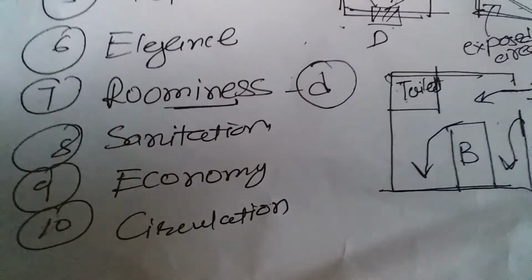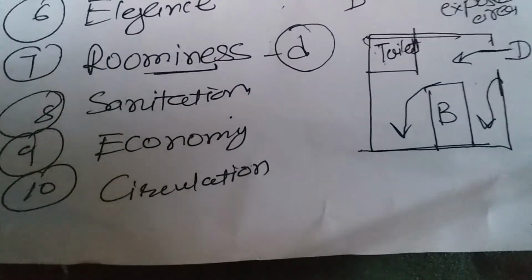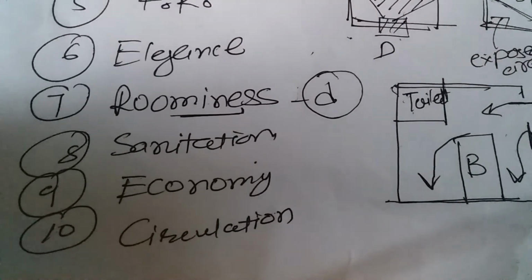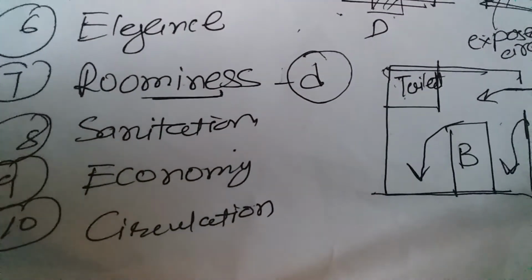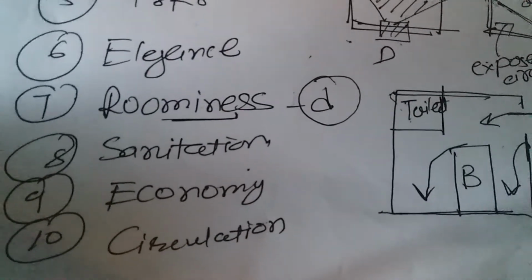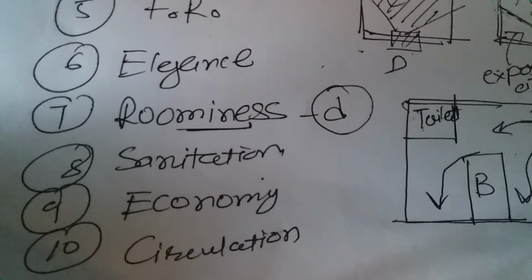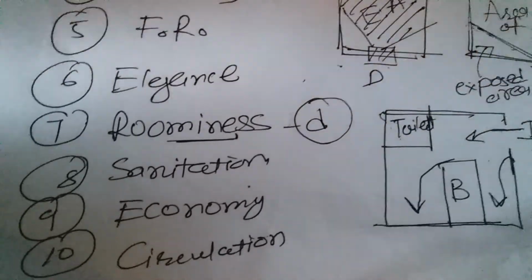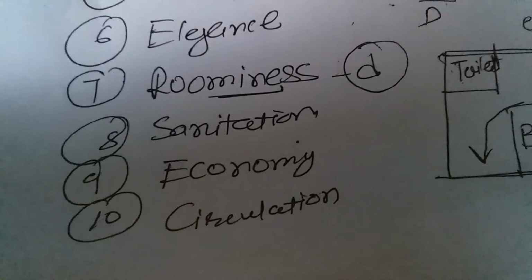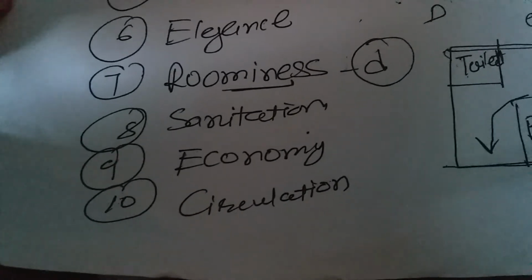Now the eighth one is sanitation. Lighting, ventilation, general cleaning and sanitary cleanliness are major parameters in sanitation. Uniform distribution of light is necessary for sanitation, particularly in schools, workshops and industry, etc. Accommodation should get light as long as it is available in the daytime. Hence, the windows are designed as vertical rather than horizontal. Generally, the minimum window area for proper lighting is 1/10th of floor area. However, it may be increased to some extent in school buildings, dormitories, factories, etc., to 1/5 of floor area.